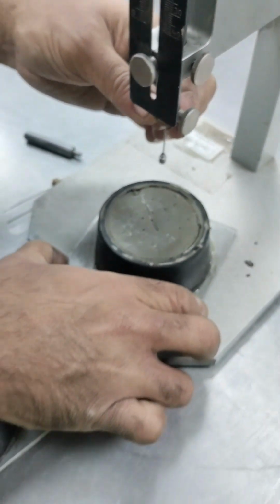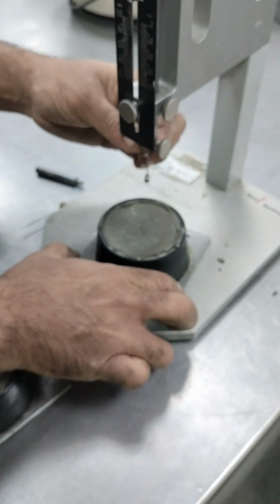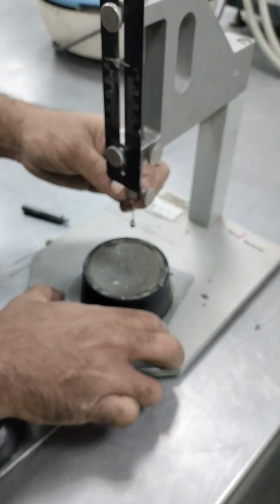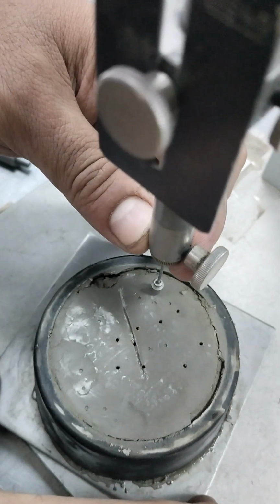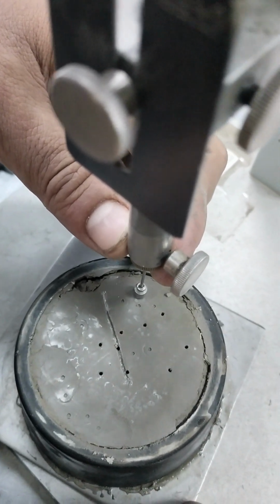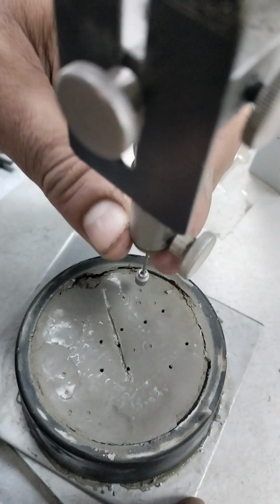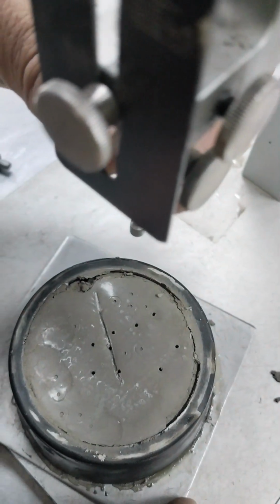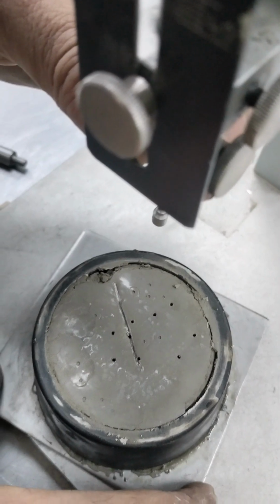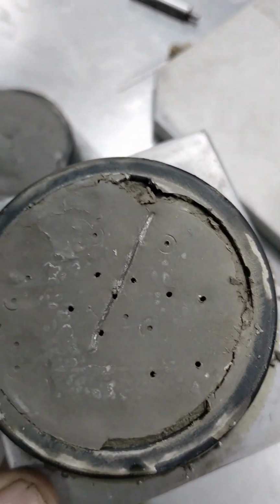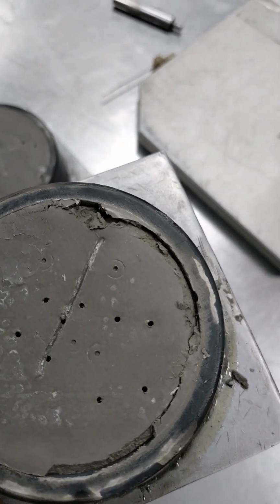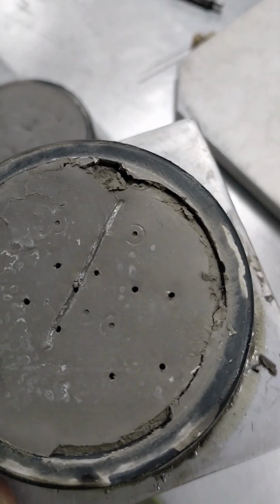Clean the Vicat needle immediately after each penetration. Record the time at which the needle first penetrates only 0.5 mm into the specimen, together with the time from 0. This time is that at which the ring attachment first fails to mark the specimen and may be accurately established by reducing the time interval between penetrations near the final setting time. The final setting time shall be confirmed by repeating the test in 2 other positions.